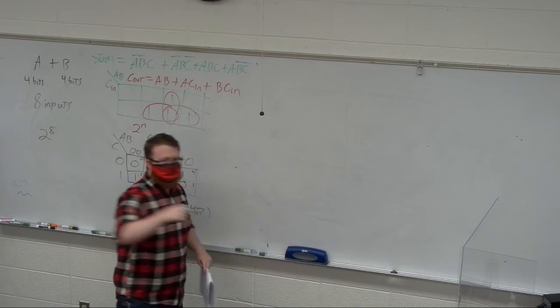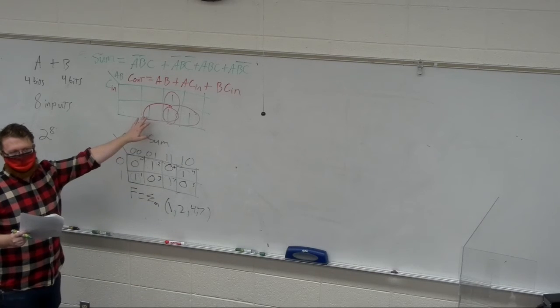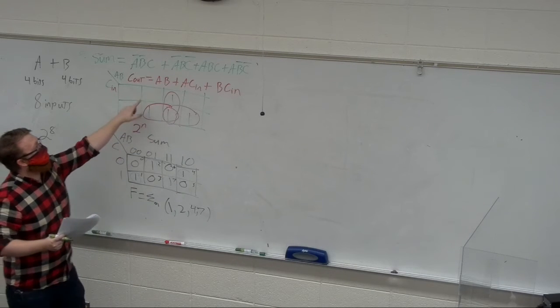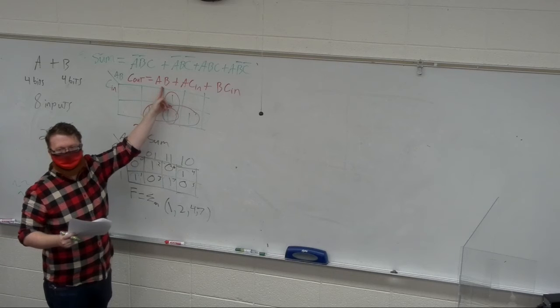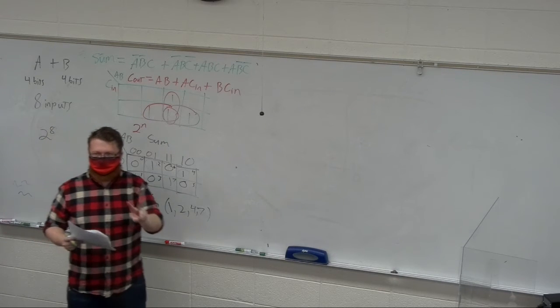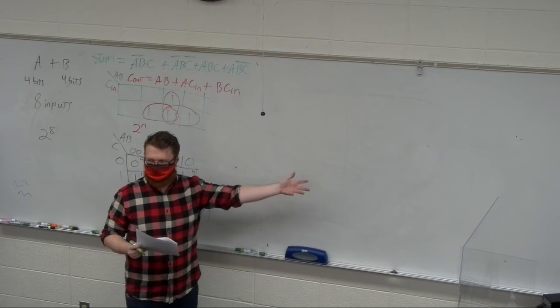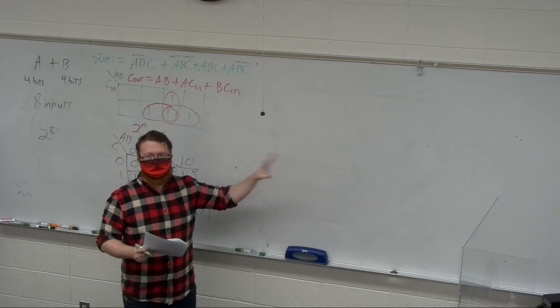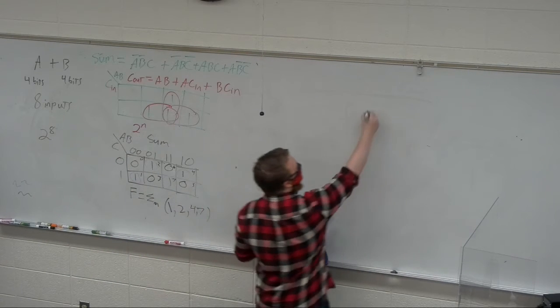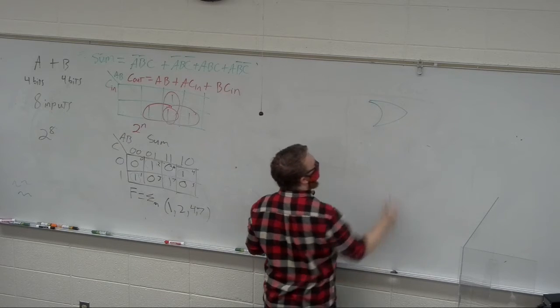So this is important. If I have circled ones, I am developing a sum of products. I'm going to have 2 tiers of gates, and we start with the output gate. We always start with the last gate. If I have circled ones, that last gate is always an OR gate.